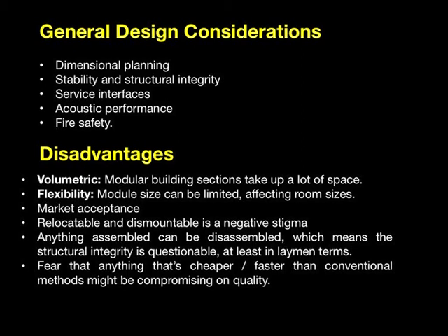How is module size limited? For example, if you take a room, you can design the room for 3 meters by 4 meters size. You can design the same room for 4 meter by 5 meter size. You can even design the room for 7 meter by 8 meter size, 10 meter by 10 meter size. You can make the rooms as big as possible. But if your room is made up of 10 meter by 10 meter size, transporting an entire 10 meter by 10 meter thing will be very, very difficult, because one thing is we won't get a transport facility that big.